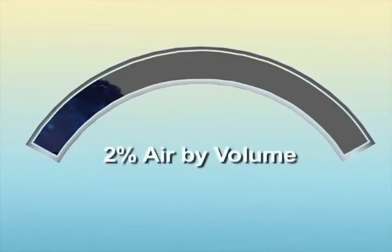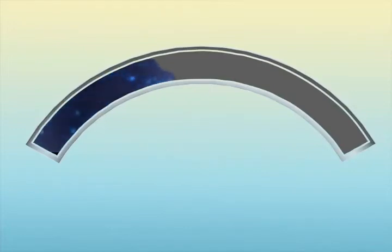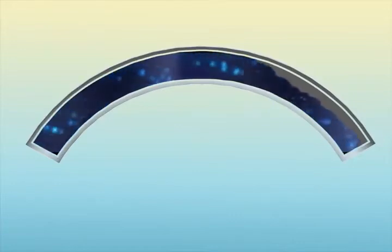Another source is the water itself. Water contains roughly 2% air by volume. During system operation, the entrained air will continuously separate out of the water and accumulate at the system high points. This 2% of air has the potential to become massive. A 1,000-foot length of pipe could contain a pocket of air 20 feet long if all the air accumulated in one location. A 1-mile length of pipe could contain a 100-foot slug. This would be true regardless of the diameter of the pipe.